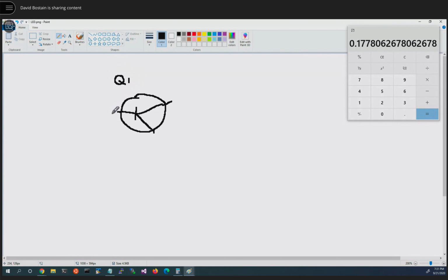In the circuit, this is the base of the transistor. This is on an NPN transistor. It is the P material. This is the collector. This is the emitter. Now there's one other notation which on a PNP transistor or NPN transistor is going to be opposite. On the transistor we're using, NPN, there's an arrow pointing out the emitter. That means that current is ultimately coming out the emitter. So current will ultimately go that way out of the transistor.